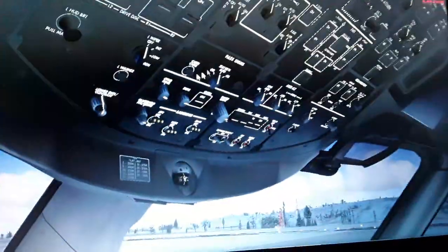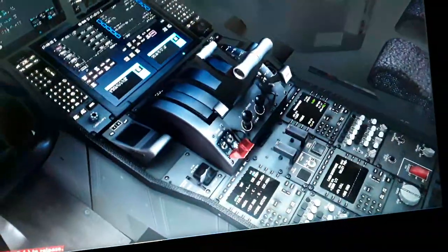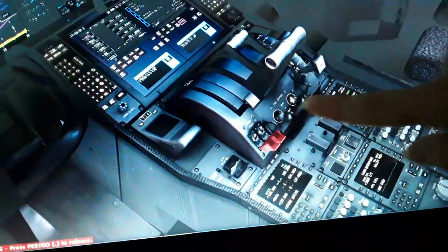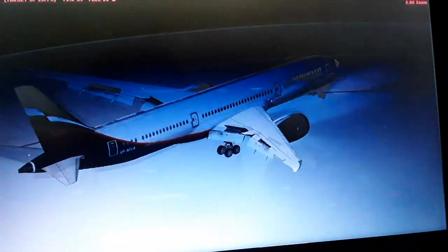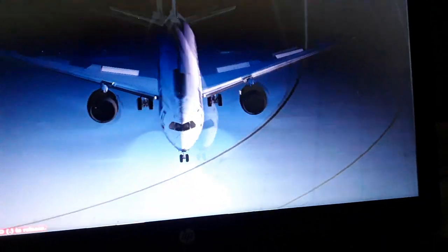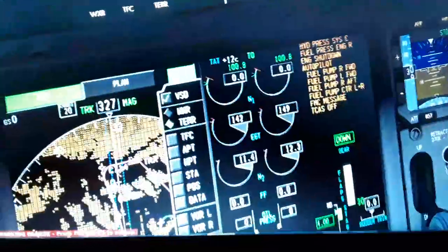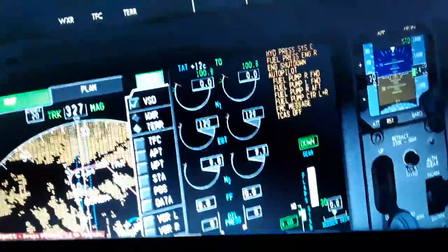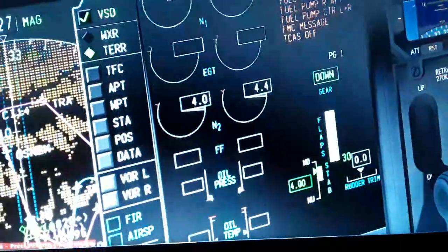So we sat down, so we need also this lighting here. We need to shut down both engines. So fuel control left and right engine to the off. You will see both engines shut down, the right and the left. So we can see the N1 and the exhaust gas temperature, the messages. We have the engines shut down now. So you can see no engines right now.